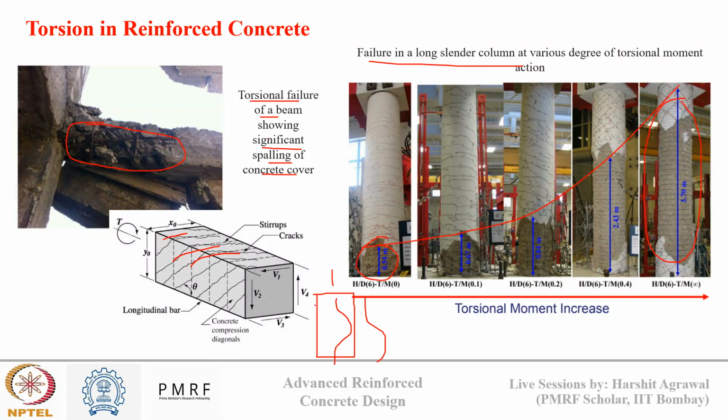However, when there is torque, there is twisting happening along this. That's why you see cracking happening all along the cross section of the member, and the surface concrete falling. However, if buckling was happening, it would have bent like this. Got the point?